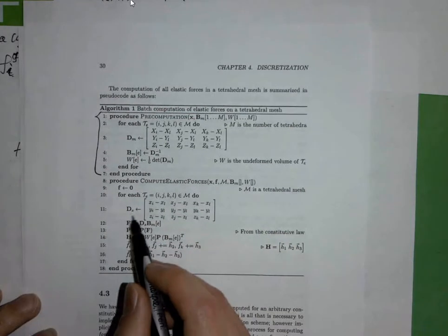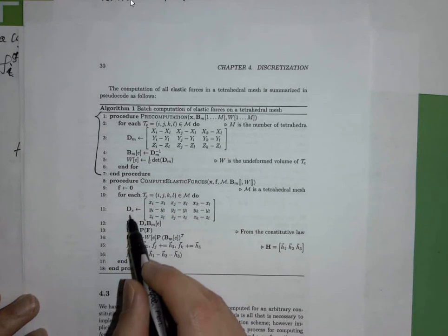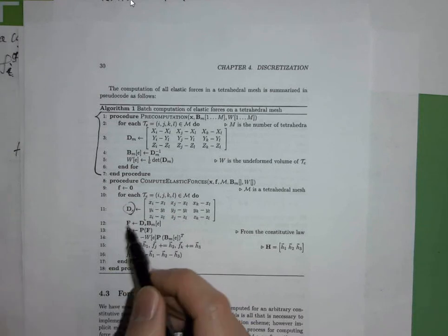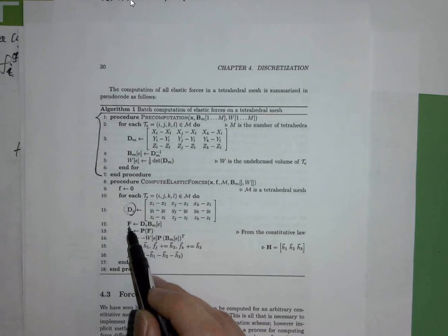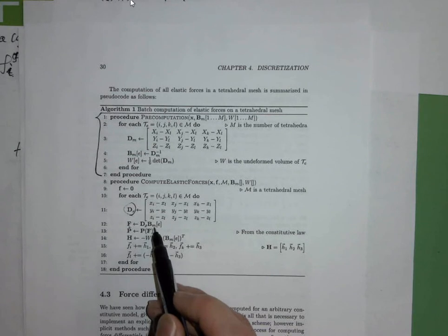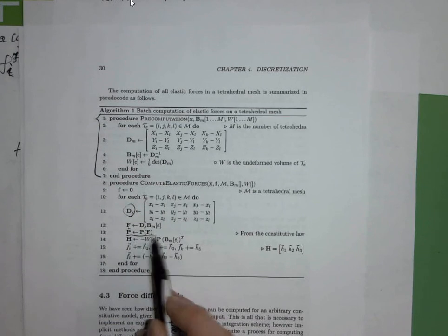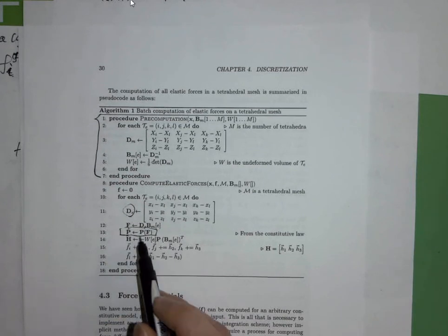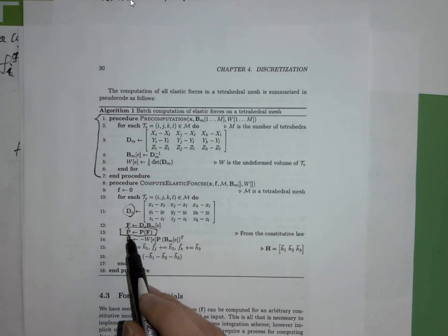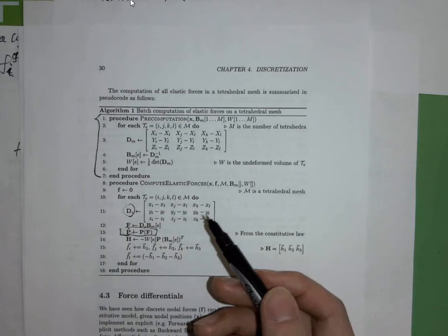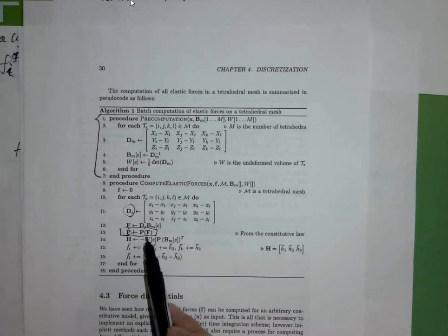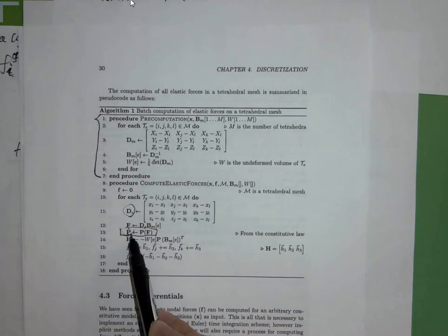And when you want to do the simulation, you want to compute force. The first thing is you calculate the current shape edge matrix, ds, compute F equals ds multiplied by dm inverse, and substitute it into your favorite material model. You can use a co-rotated linear elasticity model, or a Saint Venant-Kirchhoff model or a Neo-Hookean model, whatever you like. Get the P explicitly, and then you can construct this H matrix.